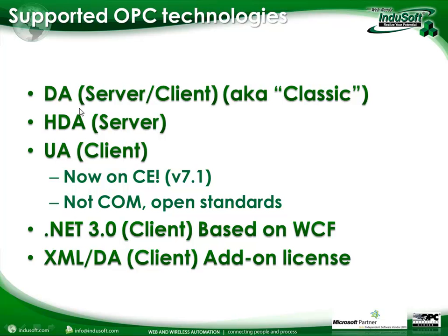OPC UA is not based on COM like OPC DA. It's built on open standards, and one of the benefits of OPC UA is it can be run on non-Microsoft operating systems, or I should say multiple platforms. Then there's OPC .NET 3.0. We can also be a client for that, and this is based on a different communication standard based on .NET technology from Windows, called Windows Communication Foundation, or WCF.